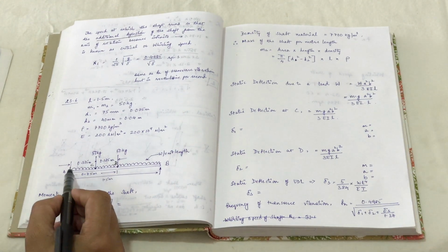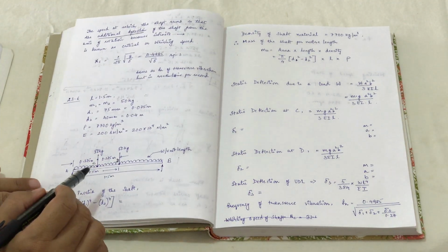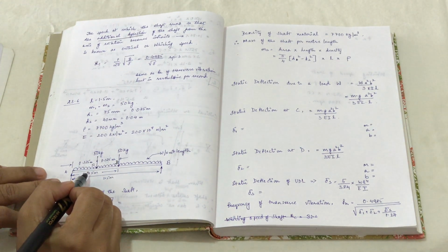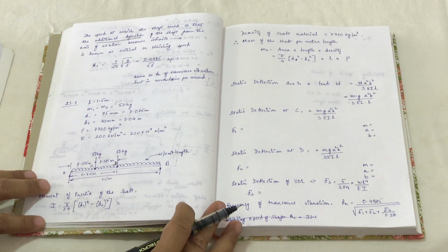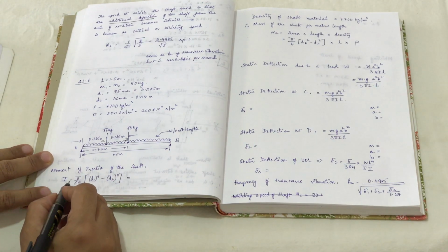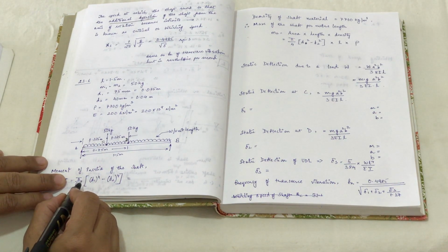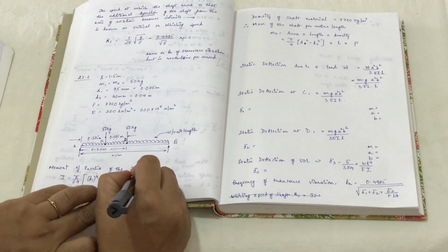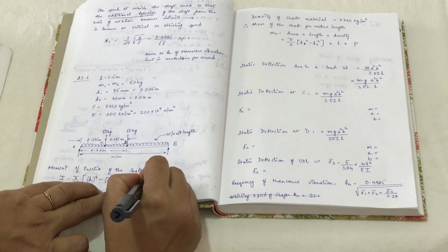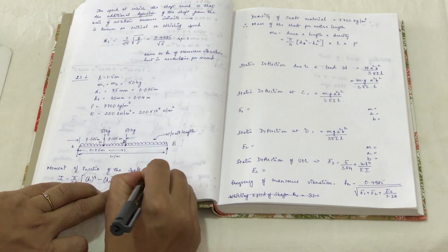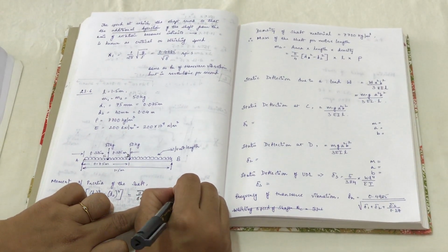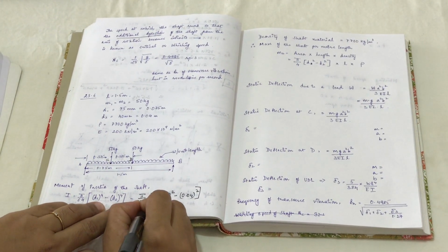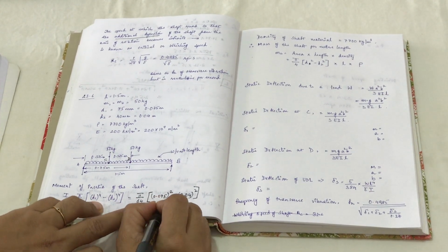So in this particular diagram, you can calculate the natural frequency of transverse vibration, and how will you calculate that? Using Dunkerley's method. So first step is to calculate the moment of inertia. So pi by 64, it's now going to be just d power 4. It's a hollow shaft, so d1 power 4 minus d2 power 4, all of you know that. So we'll just substitute the values. d1 is 0.075 power 4 minus 0.04 power 4. And the value is 1.4 into 10 power minus 6 m power 4.